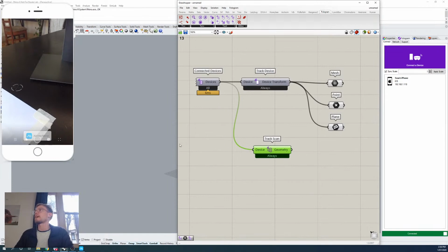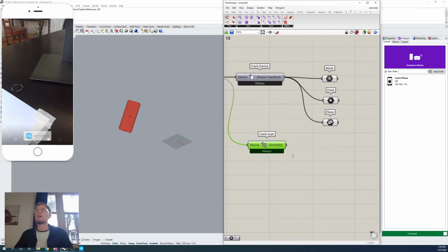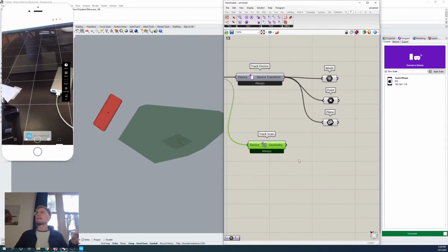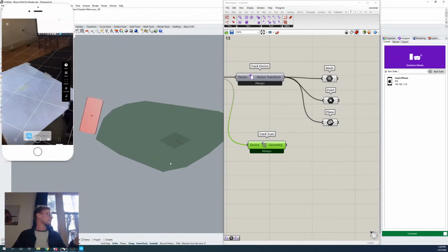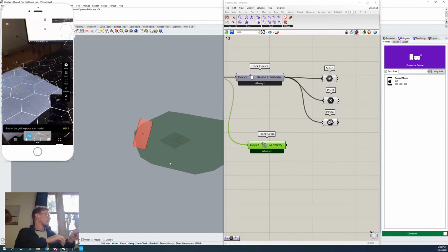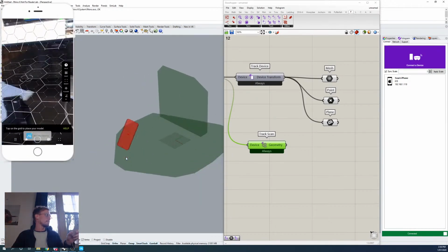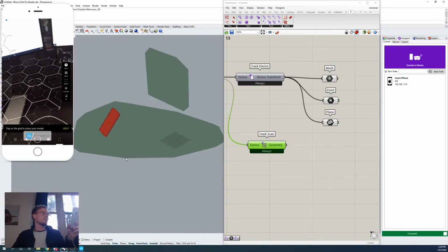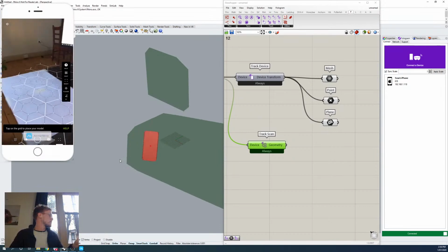And what the track scan component will output is a mesh geometry of our surroundings. So I think it'll work. You can see I go into edit mode there, and I can actually see that I'm tracking the surface. So if I go to the reset, what I'm actually doing here is tracking the location of this hexagonal placement mesh, and I'm sending that data back to Grasshopper.